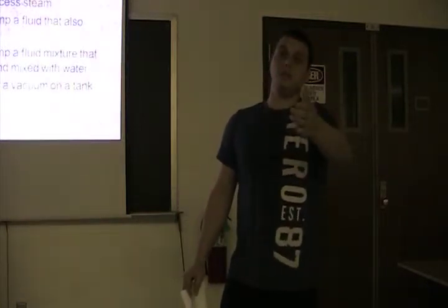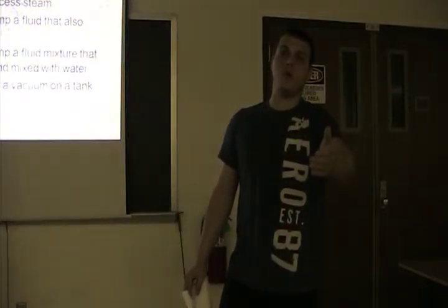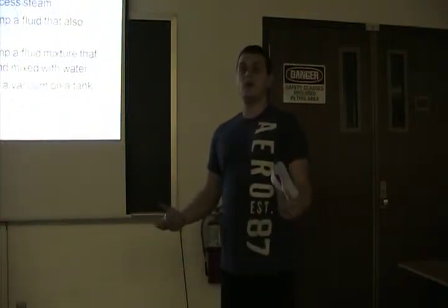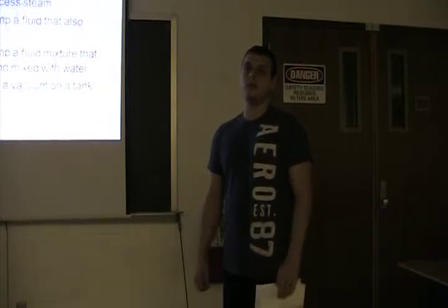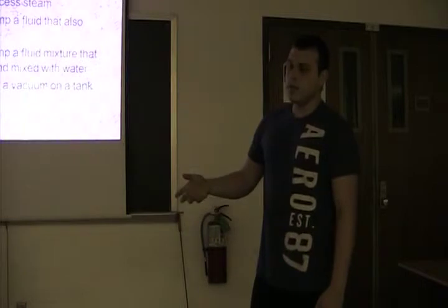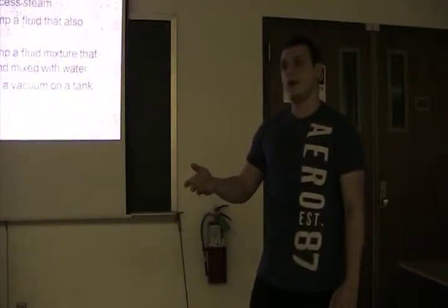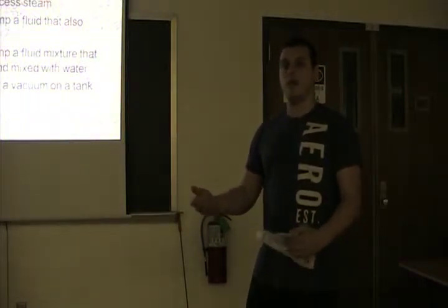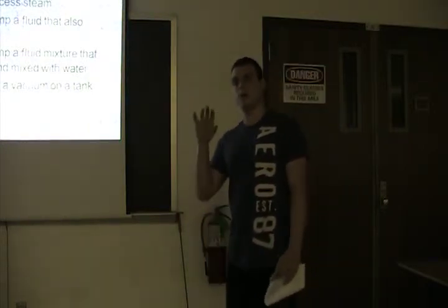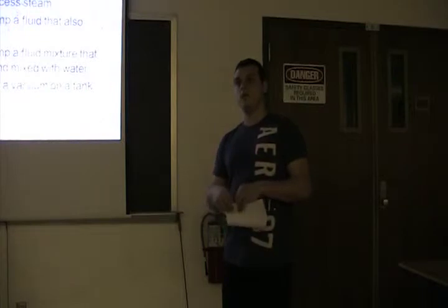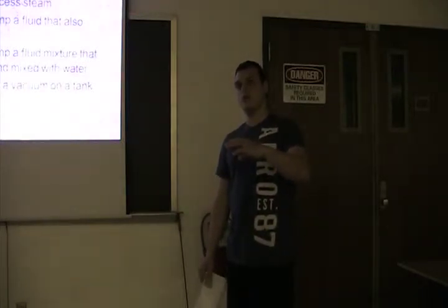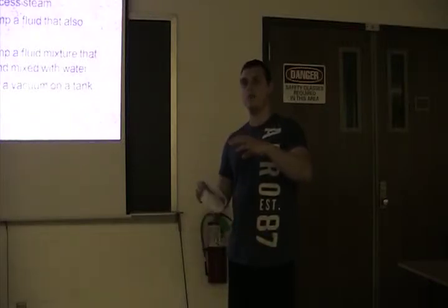So your question was, is it more efficient to use as a pump or as a heater? Well, are you using a subsonic or a supersonic? So that's going to have effects on it too, because if you're using a subsonic, it's going to pump a lot more efficiently than it's going to heat, whereas if you're using a supersonic, it's going to heat a lot better than it's going to pump, because you have more fluid being introduced in the suction tank. So you have a high volume of fluid coming into your suction tank, heating a small volume of suction water.